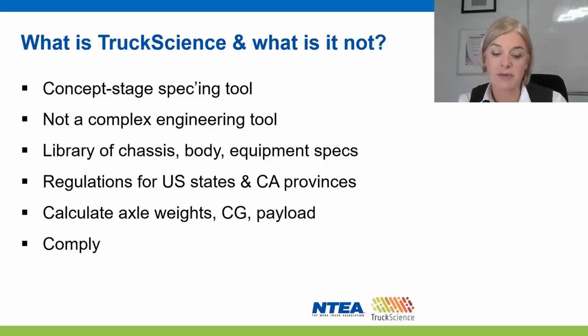In fact, we say it's a pre-CAD tool. The tool brings chassis specs, bodies, and equipment specs and legislation together. So you can calculate axle weight distribution, dimensions, center of gravity, and maximum payload, and ensure you comply with chassis manufacturer and DOT regulation limits, including bridge formula.